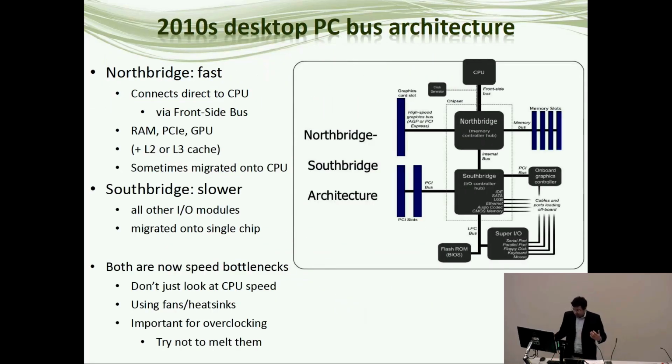So you will typically find this instantiated by this North Bridge, South Bridge architecture. Like the architecture of Edinburgh, we have a North Bridge and a South Bridge. The North Bridge is going to sit here, it's going to talk to the CPU. It's going to manage this fast bus. Maybe you're going to put some cache on here. Historically, this would have been a level 2 cache with level 1 on the CPU.